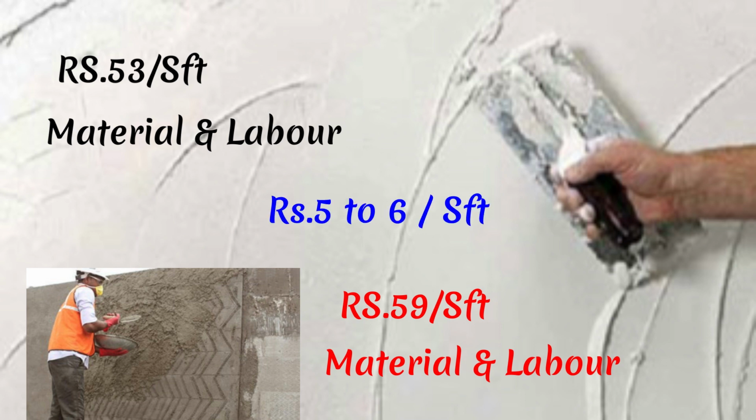So in this way we can save up to 5 to 6 rupees per square feet when we use gypsum plastering instead of cement plastering. Gypsum plastering alone is costlier than cement plastering, but when we compile with painting work we can save up to 5 to 6 rupees per square feet if we use gypsum plastering. This cost will vary according to the place and type of the material which we use in the plastering work.